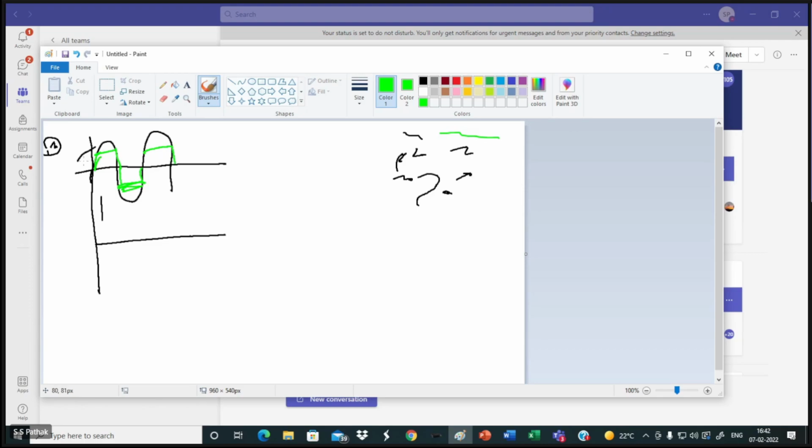Now, this voltage I am calling VR1. This voltage, where it is clipped, I call VR2. I am considering both of them as positive reference voltages, but the signal I am taking goes both positive and negative. You can put VR1, VR2 as a negative magnitude and you will get the answer automatically. Here I am considering both of them as positive.